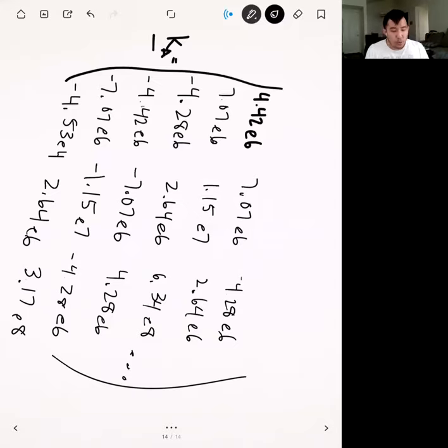Okay. And so once you have these element stiffness matrices, this is for element A. You would do the same thing for element B and get their element stiffness matrix. You would apply the boundary conditions that we talked about at the beginning. You would assemble them together, and then solve, and then you would get the solution. And so this solution is going to be different than the one in the lecture notes, just because we have different loading. But just as good practice, it might be good to run through this.